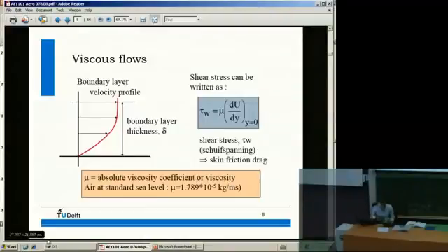Why? Because the flow has to be decreased in a smaller area, right? So what does the friction scale with? It's the steepness of this, the du over dy. And y is in this direction, u is in this direction, so du dy is the steepness of this. The steeper it is, the higher the friction, but you should look at it from this side. So if it's steeper related to this, maybe I'll draw it.